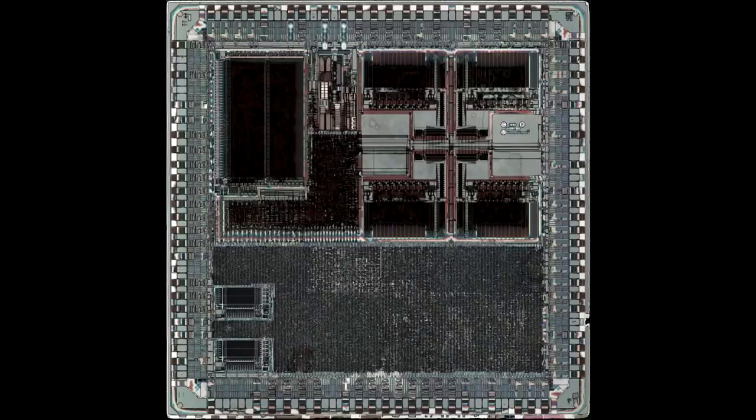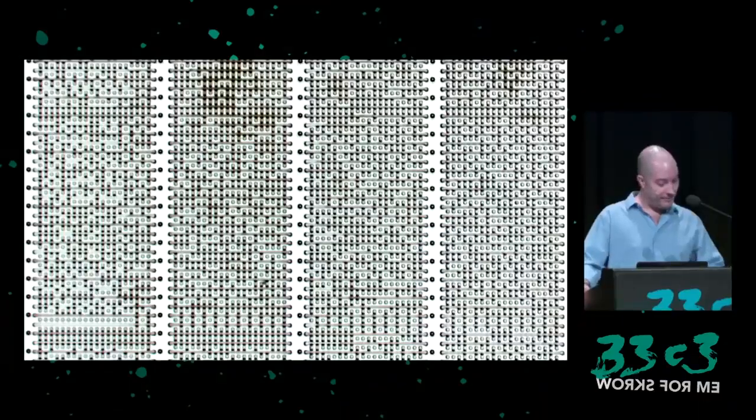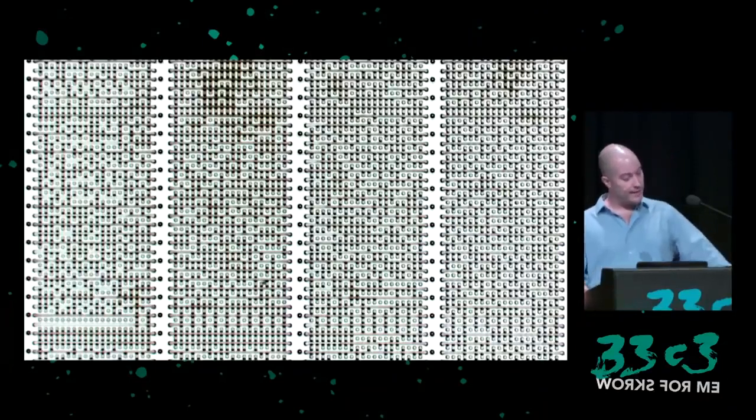Some of the areas of the ROM are now showing visible bits. The other areas haven't been etched deeply enough. So I continue to etch further to try and get a clean ROM. We can see the ROM bits quite clearly now. They're arranged in rows and columns, and in this image, if a black dot is visible, that indicates that the bit is a 1.